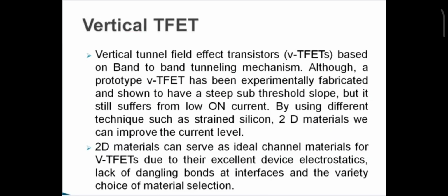The next solution is vertical TFET. Vertical tunnel field effect transistor based on band-to-band tunneling mechanism. Although a prototype vertical tunnel field effect transistor has been experimentally fabricated and shown to have a steep subthreshold slope, it still suffers from low on current. By using different techniques such as strained silicon and 2D material, we can improve the current level of the tunnel field effect transistor. 2D materials can serve as ideal channel material for the vertical field effect transistor,